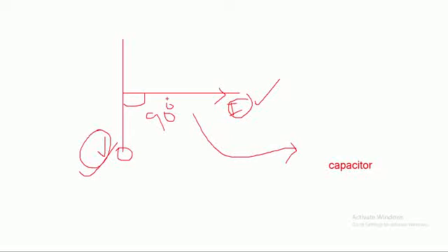As it is a capacitor, I'm indicating this voltage as VC. If the voltage you are calculating across the unknown element, when placed on the phasor diagram, exists above this line, then this one is called an inductor.